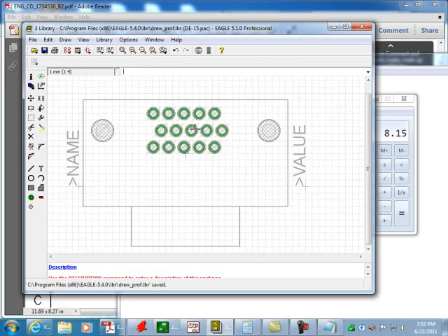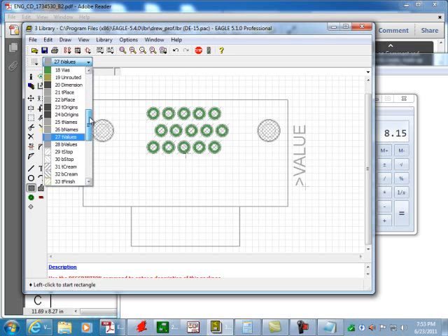There's some other interesting things we could do if we were making a homebrew board and it was going to be one-sided or whatever, or if we wanted to restrict vias, then we could do a fill rectangle. So let's say I didn't want any vias underneath my connector because I'm doing it at home and I don't want to have those little solder bumps under the connector.